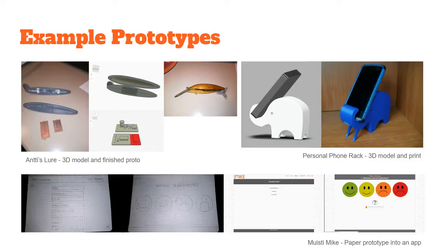And the first prototype I had actually had these supporting structures done with another kind of water soluble plastic. Okay, but it appears that you have to actually soak it in water for more than 24 hours to clean it off. It's not fast prototyping anymore. So the current prototype doesn't have any of these things. It has a maximum of minus 45-degree hanging edges.